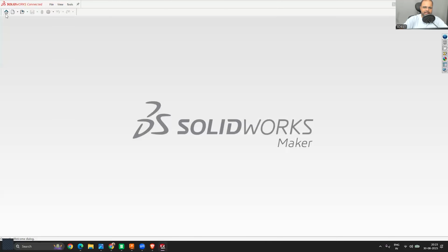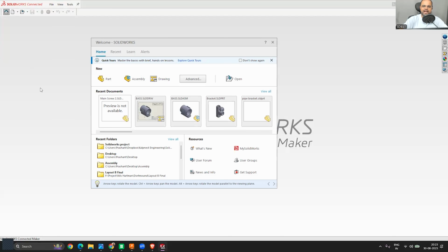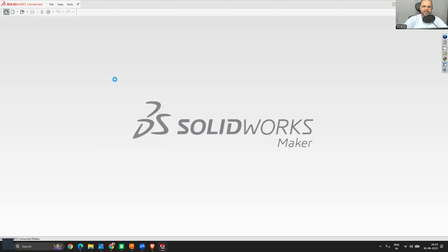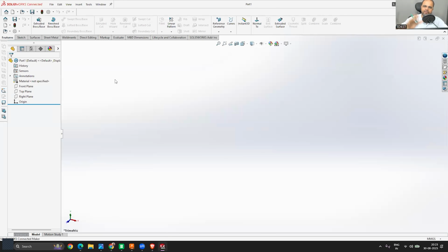Now I will simply click on home, and then we'll start a new part file. I will click on home, then we'll go to this new section. I will select this part file. The moment you click, your first part file just got started, right?